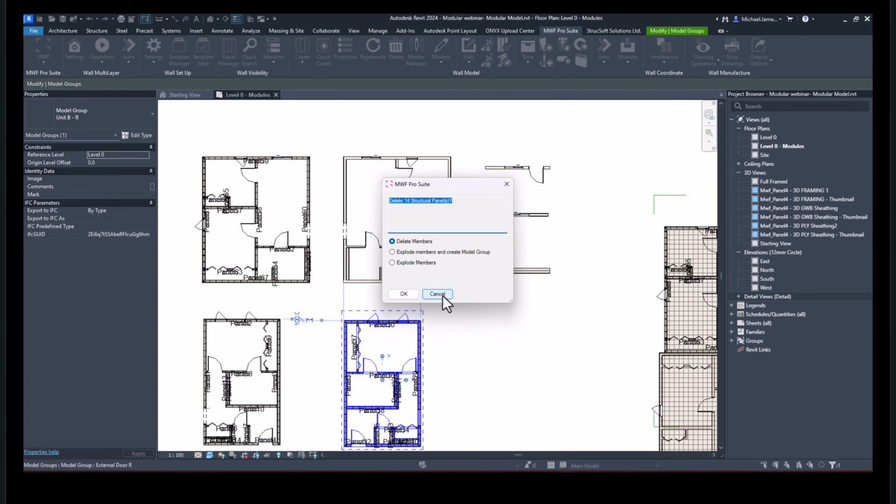When framing our multi-layer panels, it's important that we have our multi-layer template map generated. So when we go to frame our panels, all the sheathing and any secondary layers are automatically placed as well. So if I go to the wall multi-layer panel, within my settings, we'll be able to see that our walls are configured to show our sheathing and other elements as necessary.